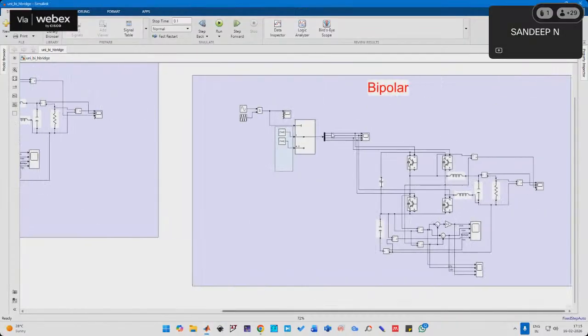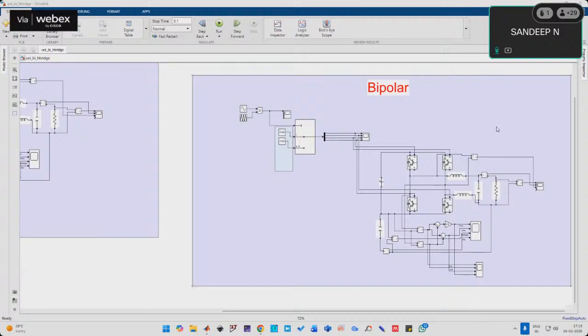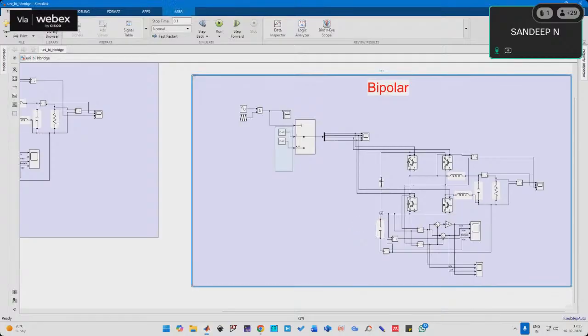Right. So what you see here is the bipolar structure, right? So we have our inverter, then we have the DC bus, and then this is your common mode attenuation setup. Then you have a load. So this is a filter, a C filter that has been used. Then this capacitor is the parasitic capacitance that is connected between the negative DC bus and the grid. In this case, it is not grid connected, of course, and the neutral point of the load.